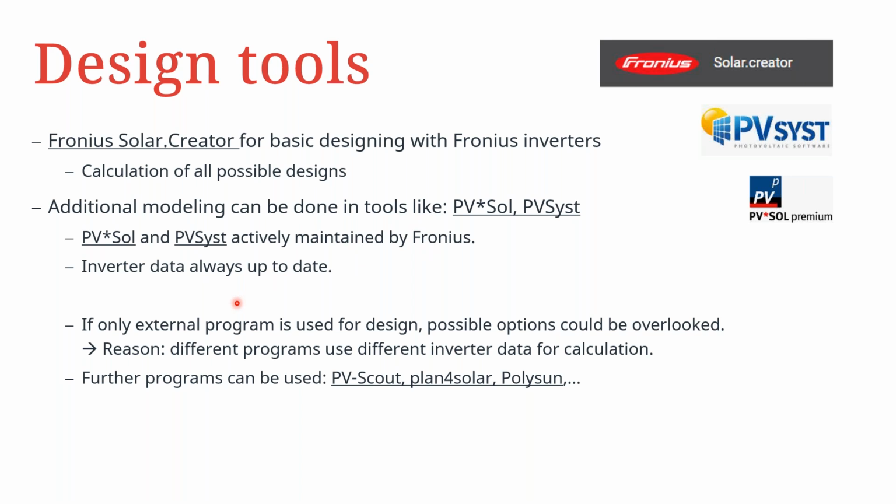However, if you use only an external design tool for commercial systems, it is possible that you're going to overlook some possible recommendations as far as inverter choice is concerned. The reason for this is that different programs will use different inverter data for calculation.